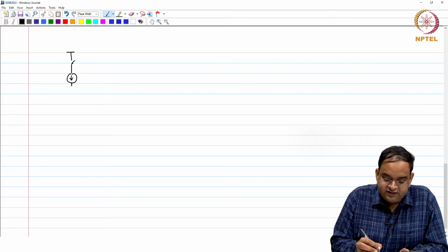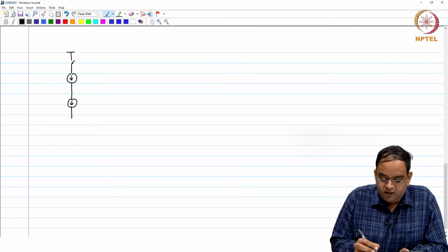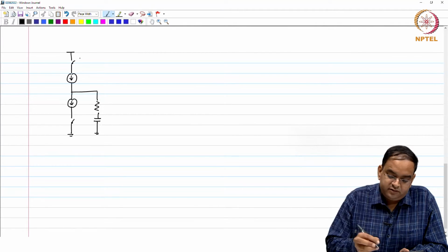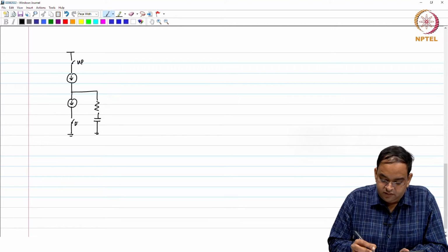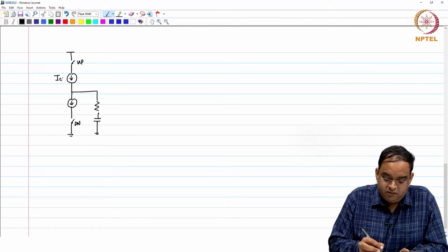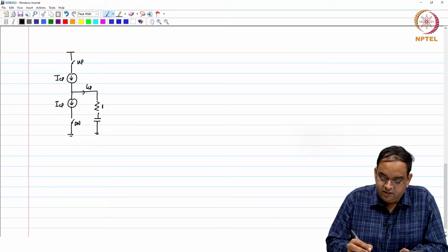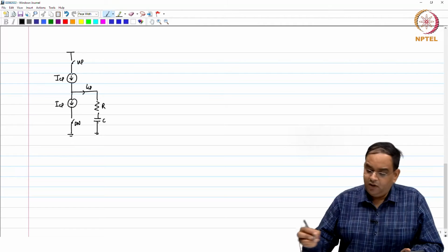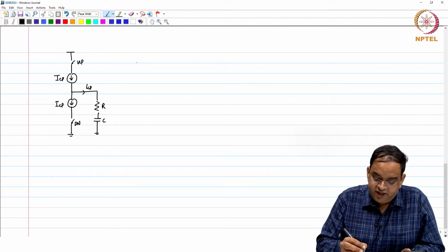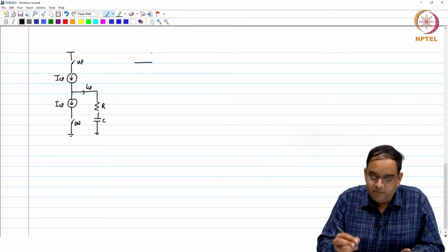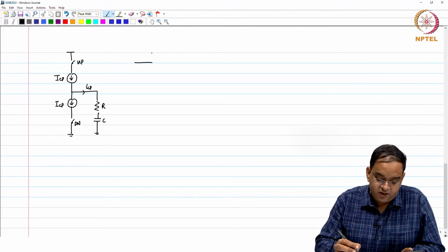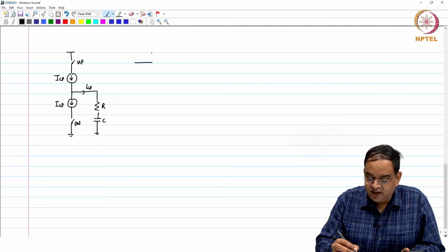So, you have this ICP followed by the loop filter response. Okay. So, this is up and down, let us not worry about up and down now, and this is ICP going in the system. Now, what happens is, we have seen this multiple times, that let us say your up and down pulses have some kind of phase error.